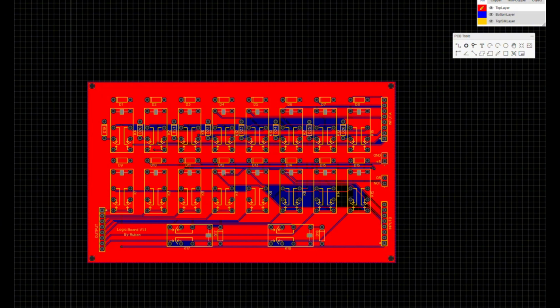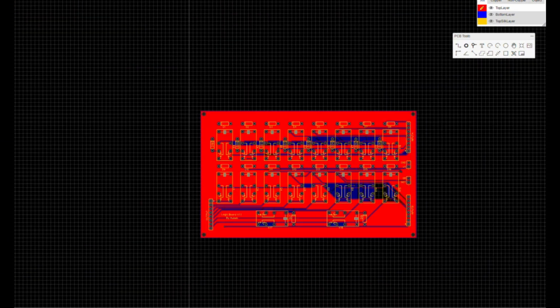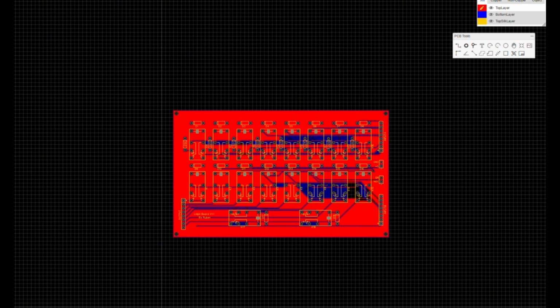So this is the logic board. We have our 2 inputs from A and B. B passes through the control unit of the ALU, because for NOTs it has to be off, because we only do it on A. By default, without any inputs or without changing these, it's always doing an AND operation, a bitwise AND on the 2 inputs.